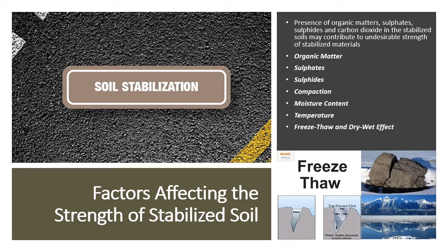The second factor is sulfate. The use of calcium-based stabilizer in sulfate-rich soil causes the stabilized sulfate-rich soil, in the presence of excess moisture, to react and form calcium sulfoaluminate, a product which occupies greater volume than the combined volume of the reactants. However, excess water over what is initially present during the time of mixing may be required to dissolve sulfate in order to allow the reaction to proceed.